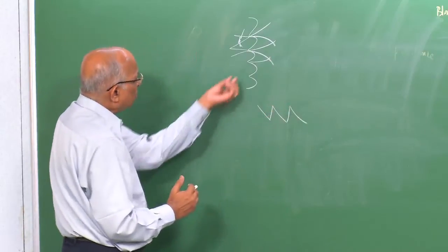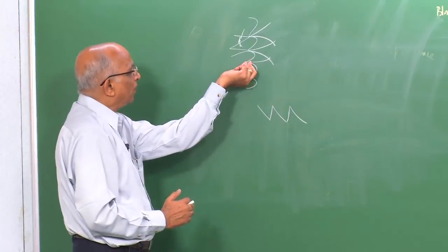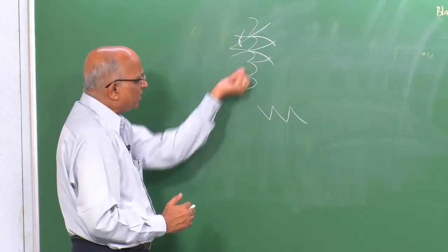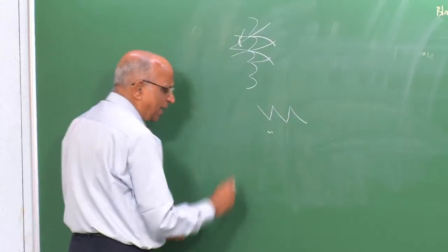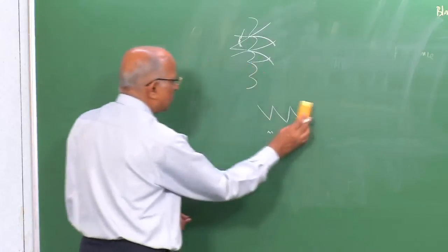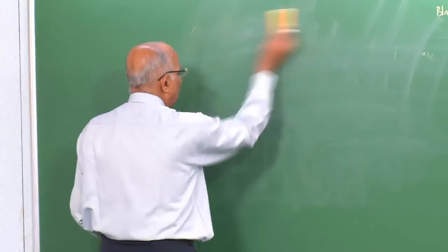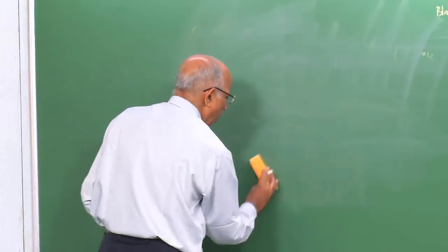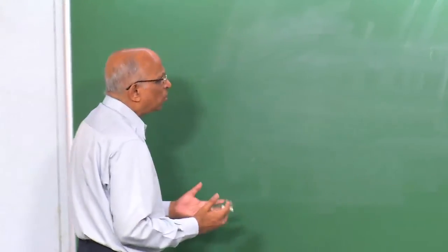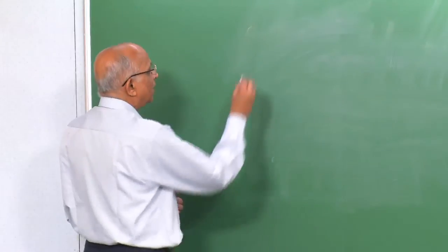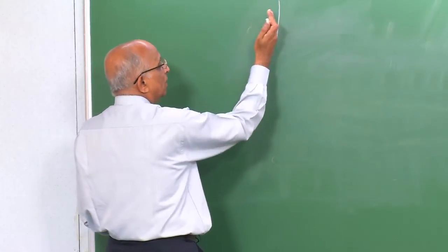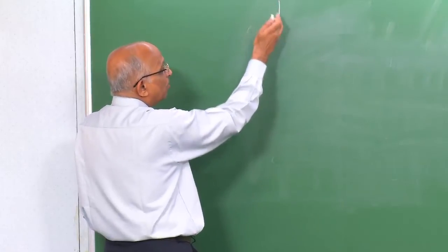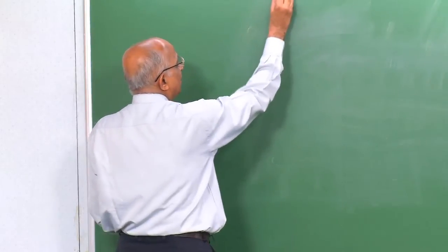But we also said if the cell sizes are small, then the variations in velocity are small. I can therefore, under certain conditions, still use my one dimensional model, and the one dimensional model has a lot of physics in it. To be able to understand a detonation, let us go back and still presume that the front is not corrugated with multiple shocks, but is, let us say, one dimensional.